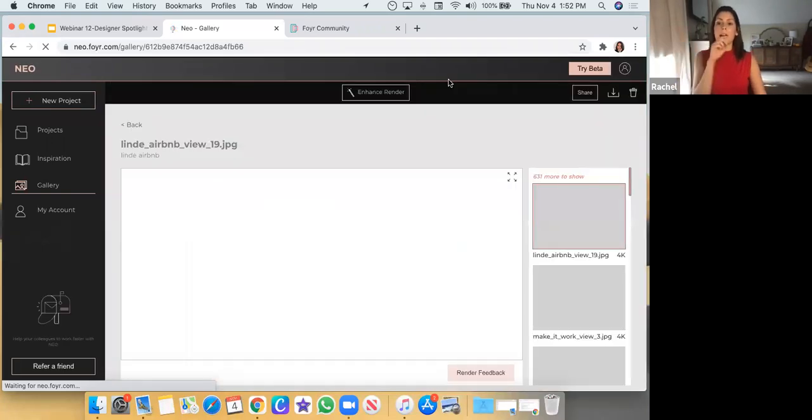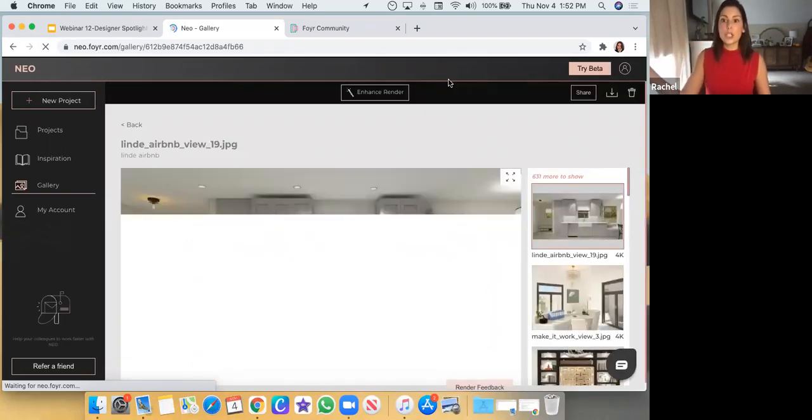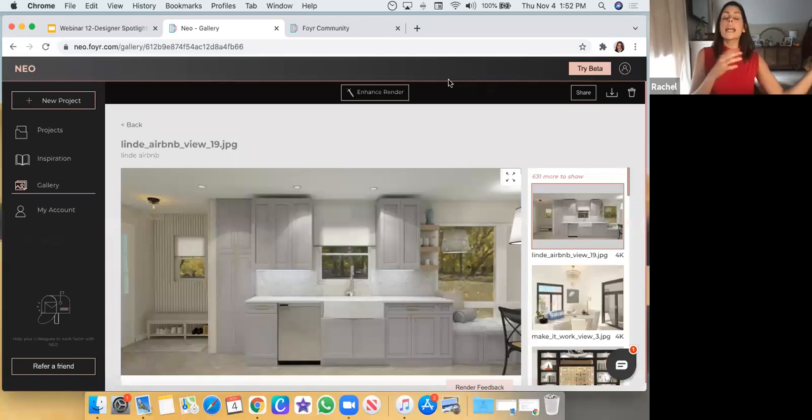So say the number of tiles on the X and Y axis was like 3 to 2 for that 10-foot wall. It's going to replicate that 3 to 2 tile on the 2-foot wide wall. But 3 to 2 in terms of the amount of tiles that we're packing in on the X and Y is going to look very different on a wall that's only 2 feet wide than it is on a wall that's 10 feet wide. So that's why you're running into that issue. It's not that it's defaulting back to the original, it's just probably that the planes that you're applying them to are pretty significantly different in size.